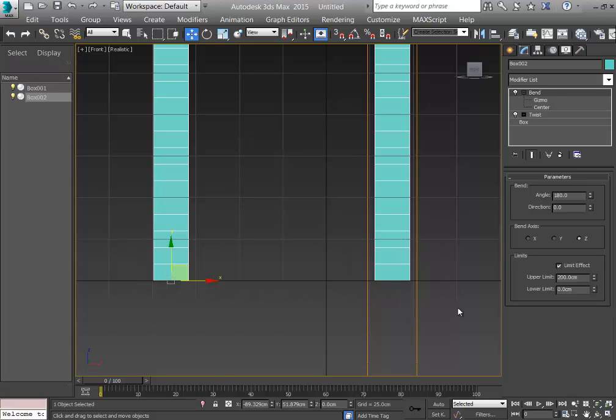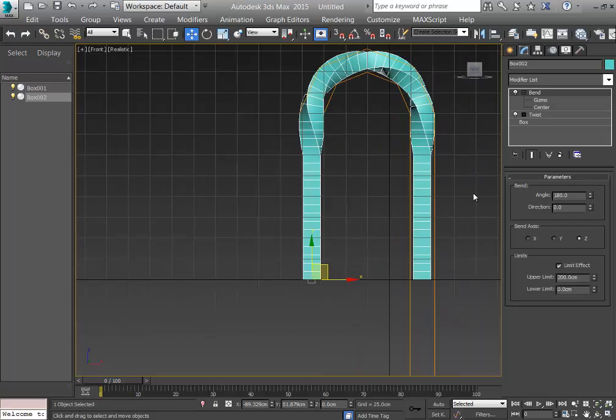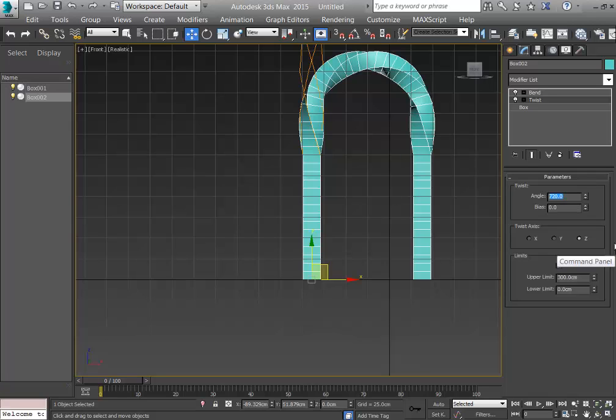You are not able to select those boxes until you make your shape either a polygon or a mesh. But there is a side effect of it. For example, if you want to change your design now, if you want this twisting to not be 720, let it be, for example, 360, you can change it. Or you can change it to 1440.